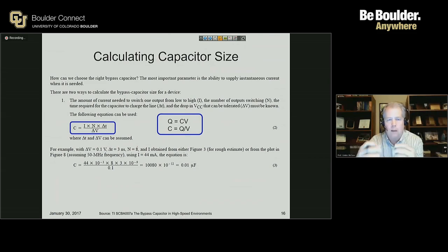Having bulk decoupling capacitors in concert with high speed or high frequency decoupling capacitors can work the same way. The bulk decoupling capacitors get refilled from the main power source, and they provide a local but not really close availability of charge. And then the little decoupling capacitors provide smaller buckets of charge that are quick to deliver to the chips.